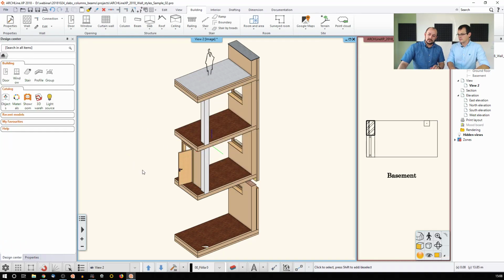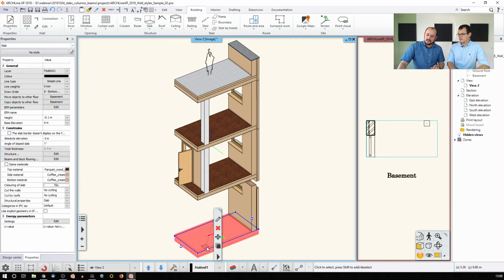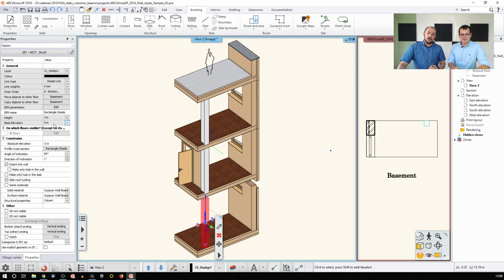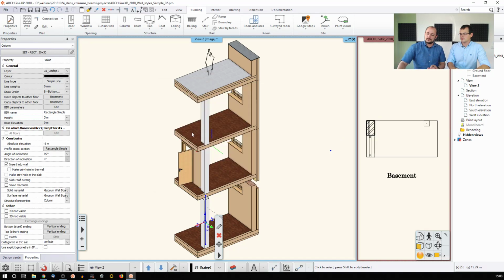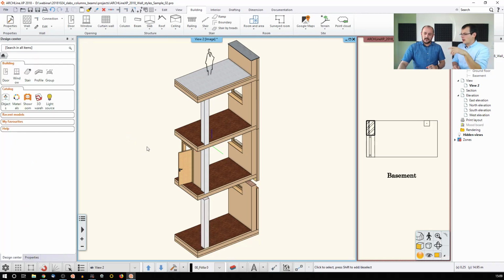The way the software represents that is actually, let me just... I think we were in another scale, so maybe it wasn't limited. The way it represents this is that instead of gray, it becomes white. So let me do it again. I just say unset, and then I change it to 3 meters, just as I did before. So now I know this is unlinked because it's not gray. Yes. So if you would crank up the height of this level, then this is going to stay at 3 meters. Yeah. Now it wouldn't change.